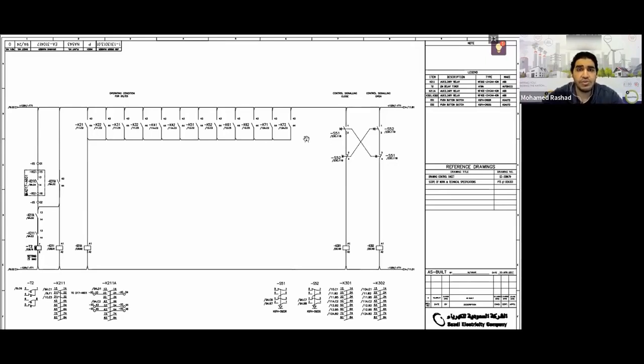whether it's the breaker, the disconnector switch, or the earth switch. As for the part in the middle here, this is a part we refer to as the double operation. Double operation, let's understand what it means. As for the last part, we refer to it as long runtime or runtime exceeded for the DS and ES. We've actually studied this part before, which is the topic of when you're in emergency mode, meaning you're standing in front of your cell, you choose select with close or select with open.